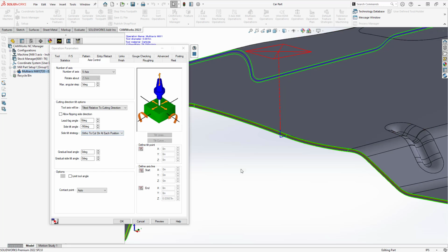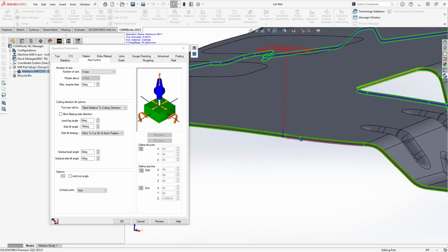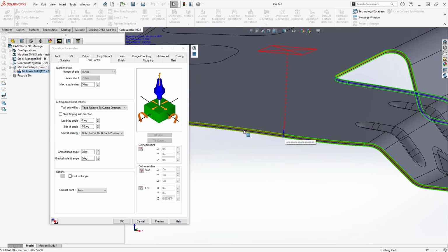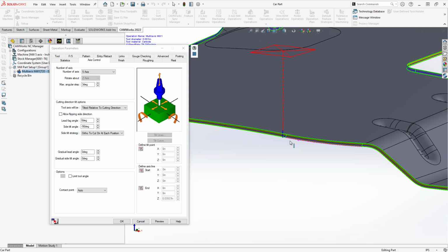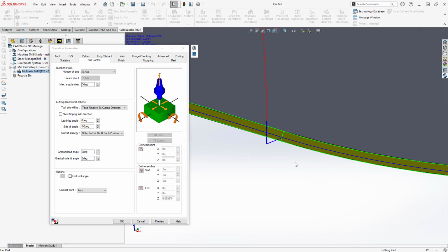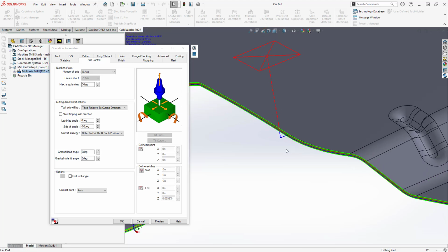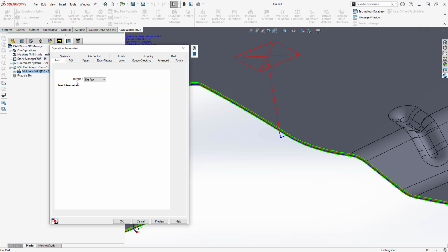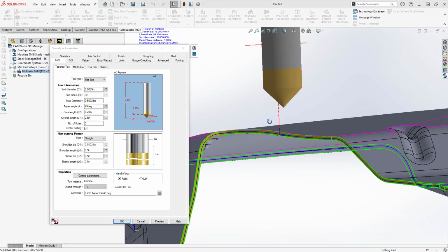Orthogonal cut direction to each position. I just wanted it to be perpendicular to the surface as it goes along. I didn't want it to be following the isolines of the yellow surface. You can see that the isoline would be kind of on an angle there. So overall, again, very similar to 5-axis. We're using a tapered mill here. It has kind of an angled surface. So by setting it to 90 degrees, we're actually getting it to almost do an approximation of a swarf cut.